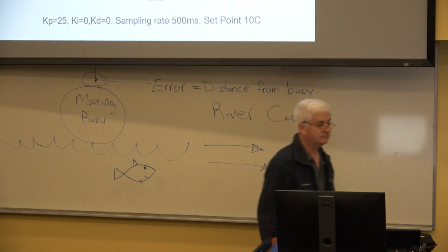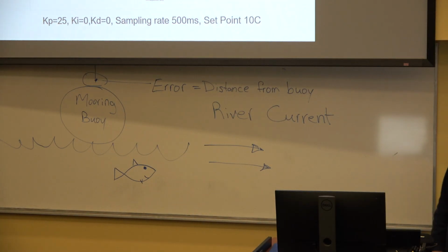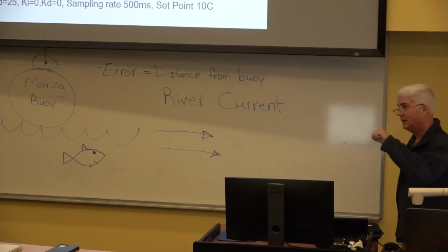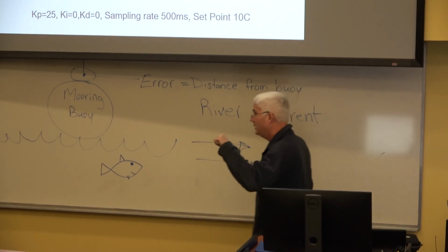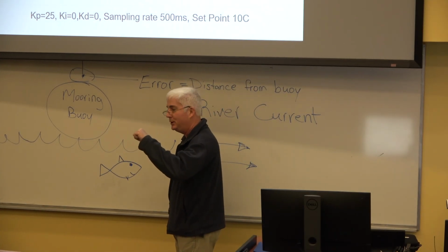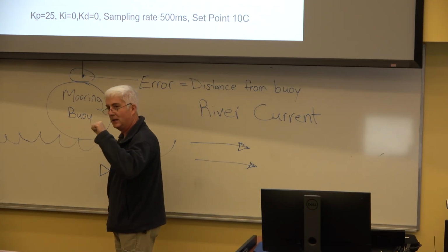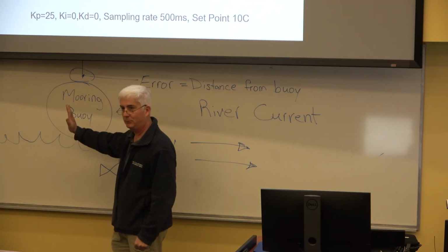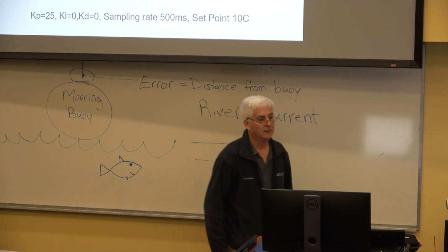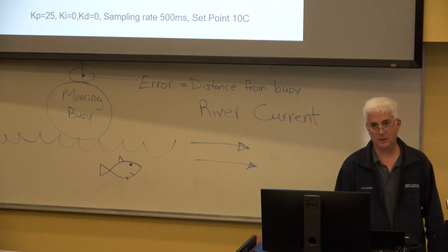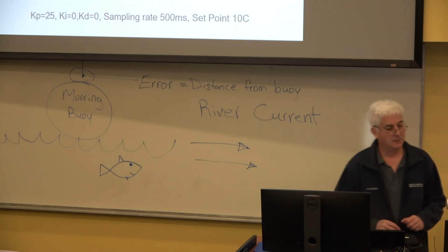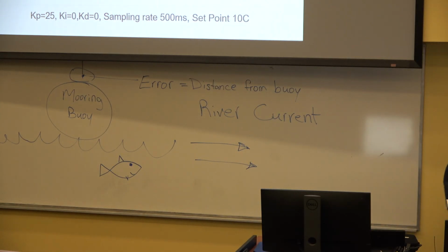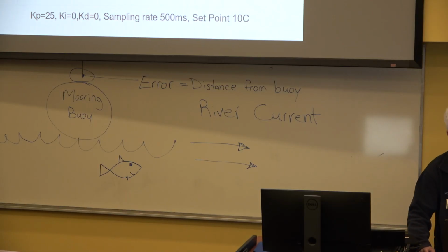And eventually, yes, in fact, I can grab onto my mooring buoy, and I stay at set point. If I'm light on the throttles, if I've got a low KI value, then I can just inch up nice and slow. KP dies off. My time integral is bringing the throttle up, and I settle right at set point. Okay. That's what you get when you're critically damped. So let's see that in this analogy, in the hardware.